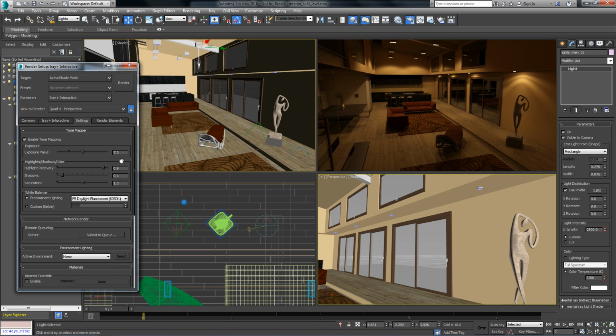This is looking good, but the color temperature feels a bit warm. It's because it was set for natural daylight. So let's adjust the white balance for the interior lighting. That looks better. Now, let's go ahead and create a different IBL.